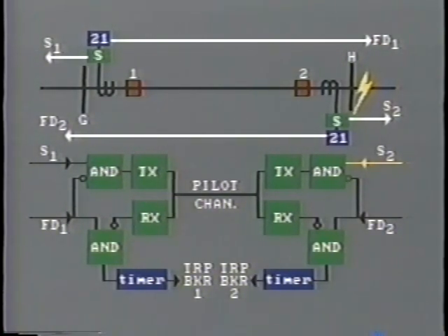Convention tells us that the logic circuit reverses the signal. That is, a 0 input signal reverses and becomes a positive signal. As this logic box shows, it requires 2 positive input signals, one from the fault detector and one from the starter relay. With these 2 positive signals, it initiates transmission of the blocking signal.